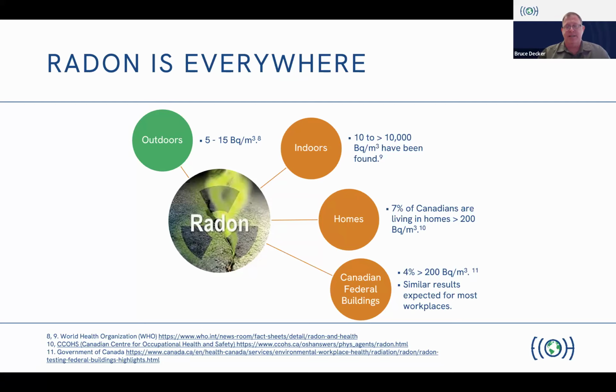The federal government tested their buildings, and they found that about 4% of commercial style buildings tend to exceed the action level of 200 becquerels from Health Canada. And with my 7 years experience of testing just commercial buildings, thousands of them across Canada, I find very, very similar results.